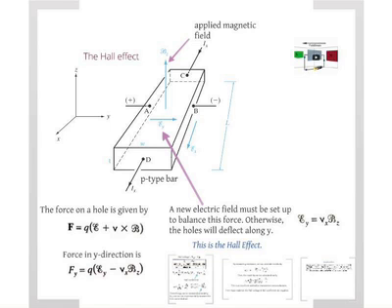And that something is essentially an electrostatic field. A field gets set up. A built-in field starts building up within this material, which opposes this force. It becomes equal and opposite to this force and prevents the hole from going this way. Physically, the way this happens is very straightforward. Some of the holes initially come to the side. Once you have a few holes there, which means that you have a positive charge there relative to the other side, you set up an electric field which opposes more holes from coming in. Right? It's as simple as that.